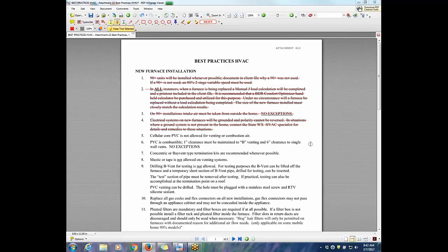Okay, we know how hot those liners get. Flue gases from the water heaters between 300 and 500 degrees. That PVC will melt, it will fail. Seen it happen firsthand. We had that last week with single wall.